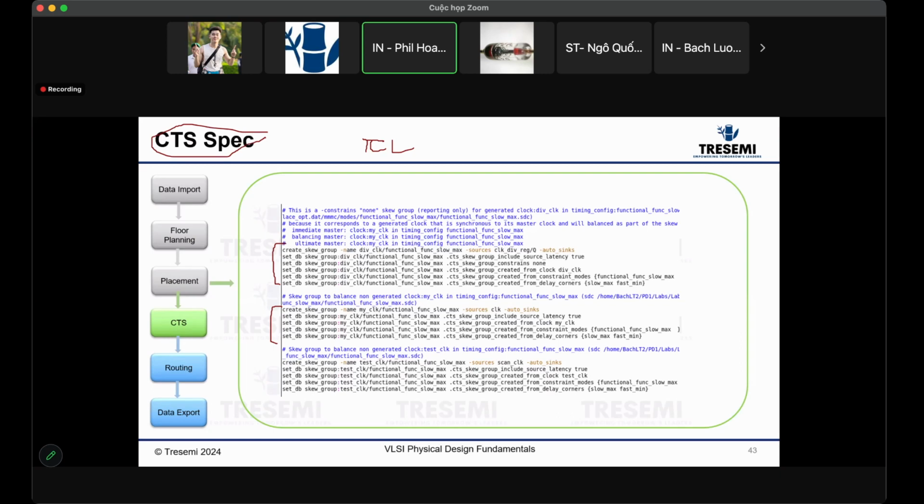Yeah. So for similar designs, it's straightforward. And he'll say, for our lab, which is a simple design, you can go with the default one and let the tool figure it out. But I'll have you do an additional one. Okay. In the next one, we'll talk about different types of clock trees and when to use them. So you see different scenarios. That will also give you a picture of the complexity of the clock trees and how important it is for you to build the right clock tree to meet your target, and the impact.